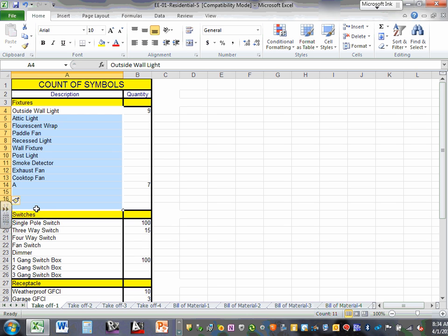If the circuit is 12-3, it would be nice to use the same, like if I were you guys, I would use, for number 12, one color, for number 14, one color. If it's 12-2, I just put next to it 12-2. If it's 12-3, I put 12-3. Did you guys see that next to that color? So color code your circuits. Color code your circuits.